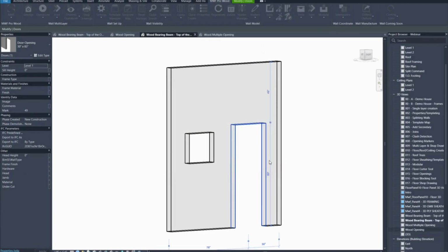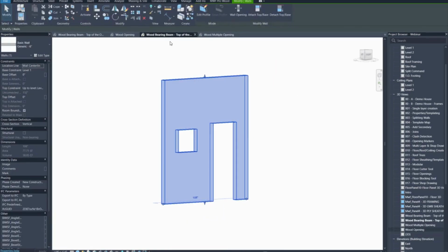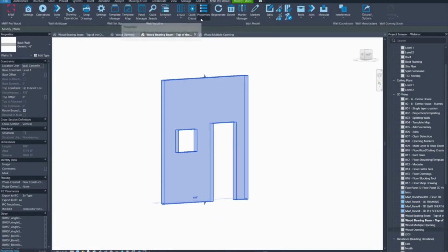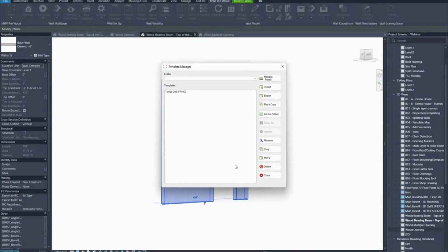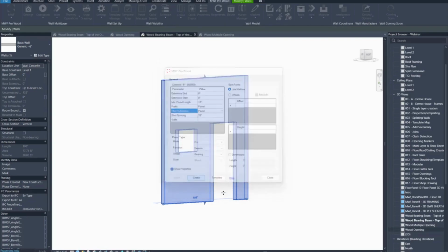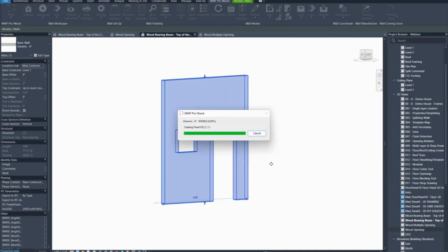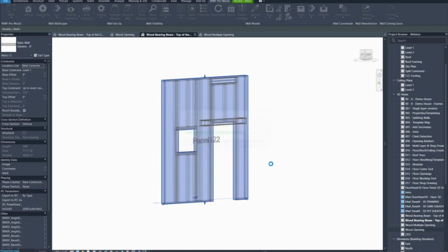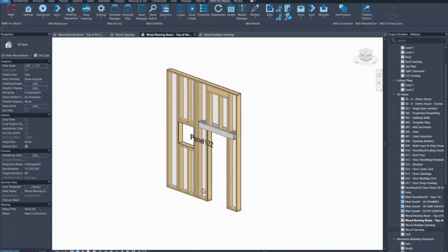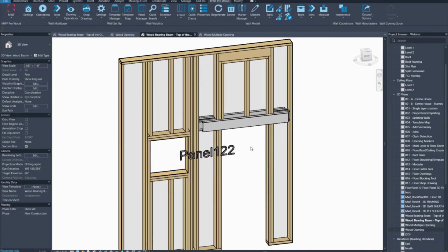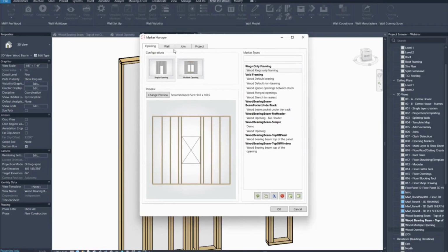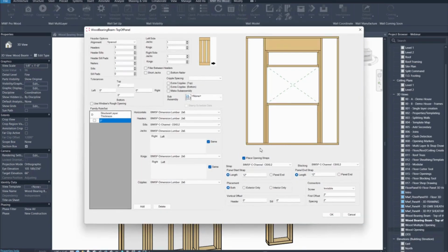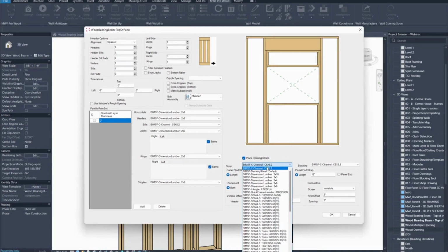Top of the panel, we assign that marker to this opening, and I'm just going to go ahead and create this. Would set as active, close, and create. I think I went with the different member because this doesn't seem, it's actually top of the panel if I'm not mistaken. Yes, as you can see, I have the wrong family selected here for the opening strap.